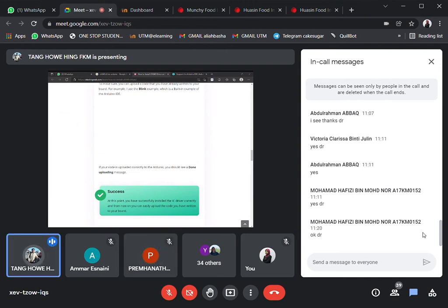Yeah, you need to try, but basically the idea is that you need to install CH340 first, if let's say you are using the China board, and then later on you need to install the Arduino IDE. These two are a must. You need to install these two first so that your computer can detect your Arduino Uno board. Once your computer detects the Arduino Uno board, that means you can now start with the program.